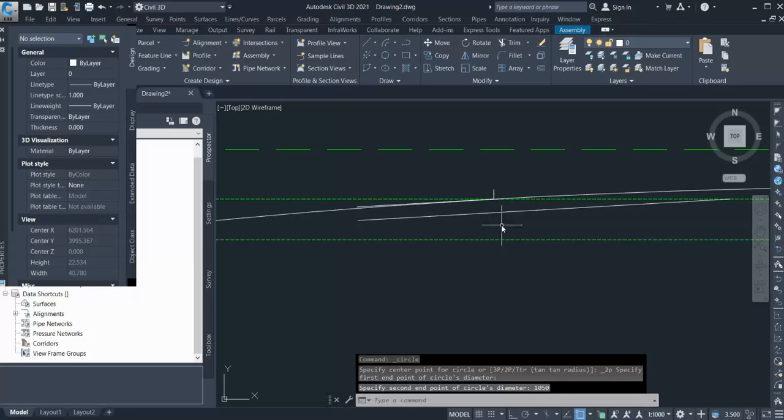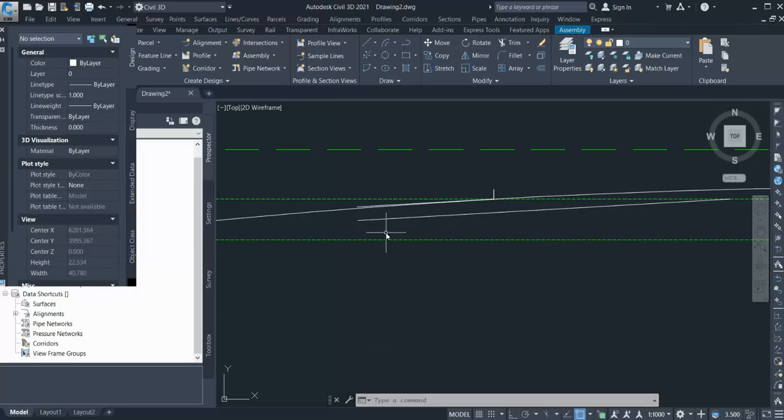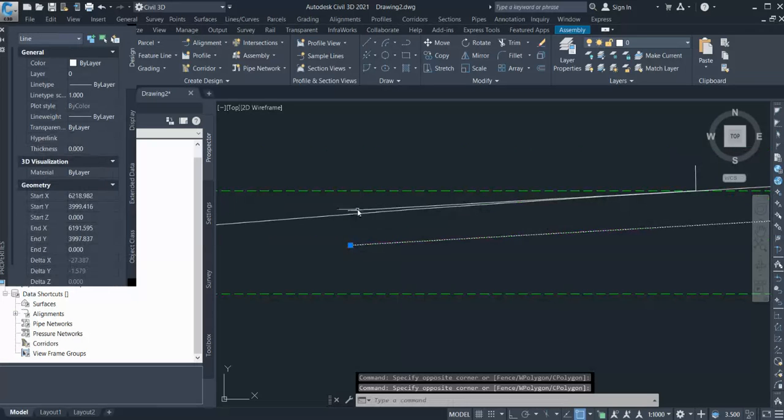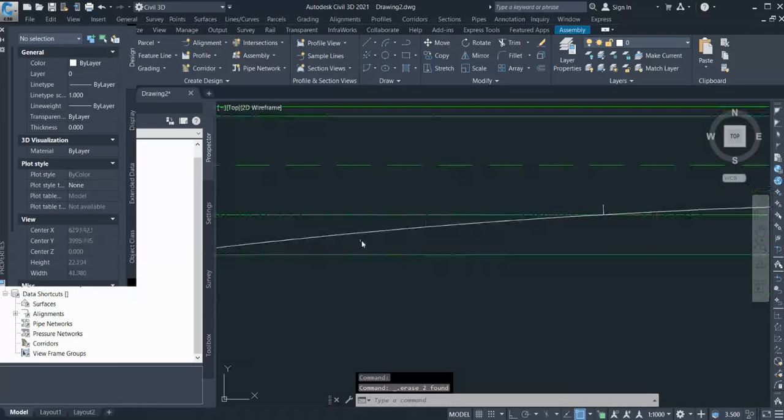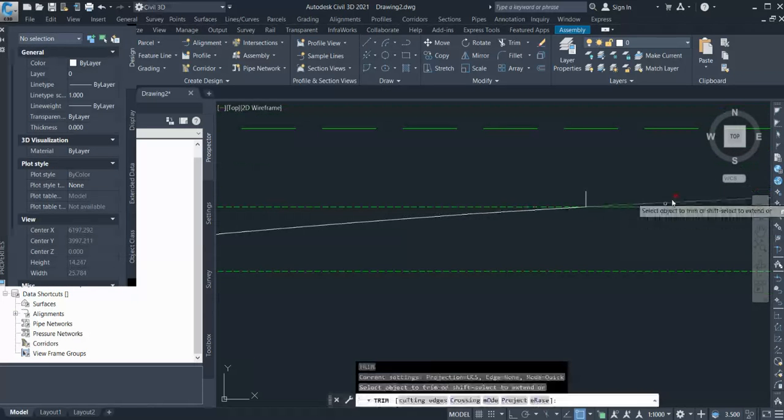Now the loop or any slip road, the diverging lanes, the speed for that is less than the main line, so it should be either 70 kmph or 60 or 50 kmph. So your loop will have that much speed. That also depends on what radius you are getting and what super elevation value you are getting, so you need to check the country standard again for that. To begin with, you go with the highest radius. So I provided the higher radius, so I don't need to provide super elevation when I start diverting. Delete this.